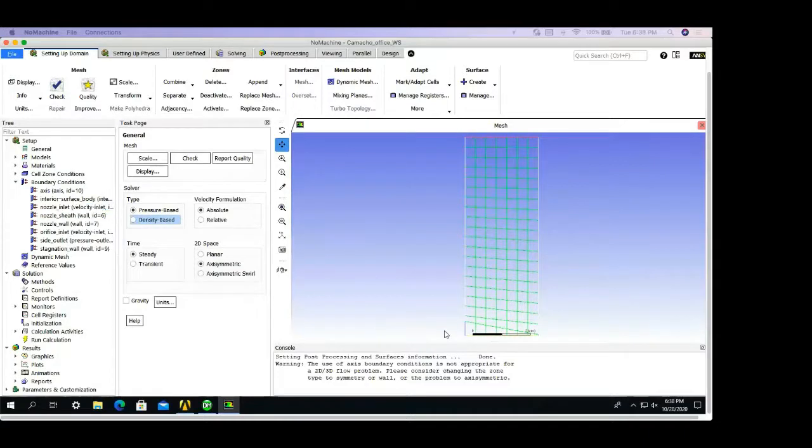So when we're defining a boundary condition, we define the nozzle inlet as a velocity inlet profile, and we provide it with the inlet velocity of the mixture gas and the mass fractions of the mixture. ANSYS prefers mass fraction versus mole fraction. So unless you actually click on the button which says mole fraction, working with mass fraction is just easier with ANSYS. And we provide the temperature, velocity inlet, and species concentration.